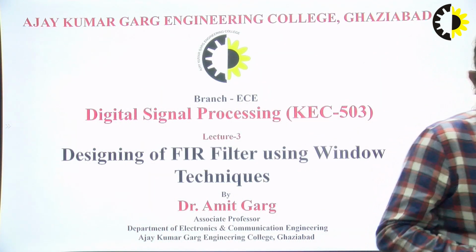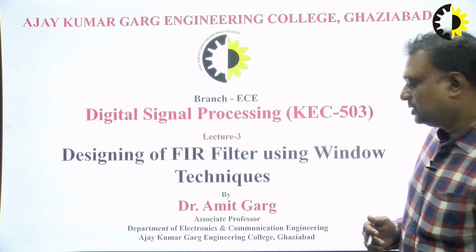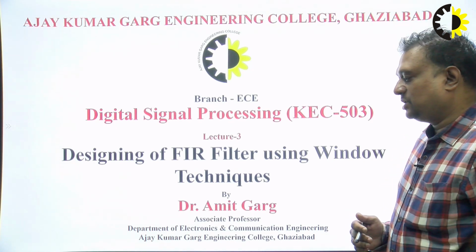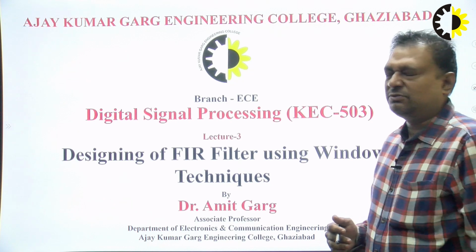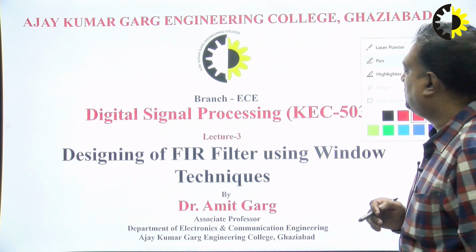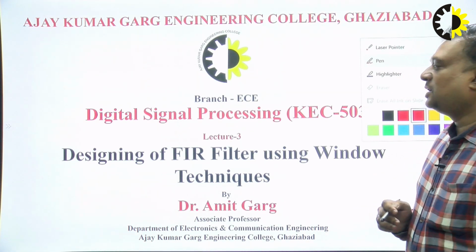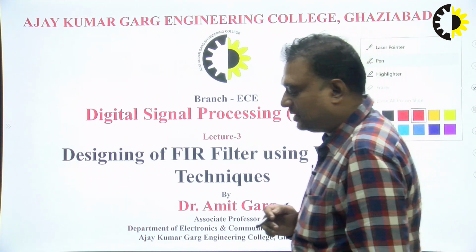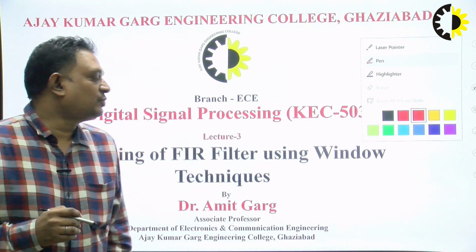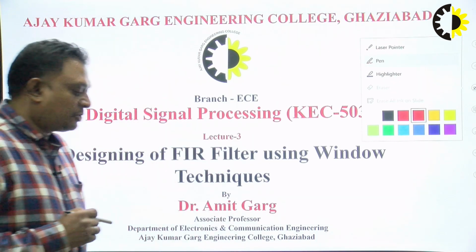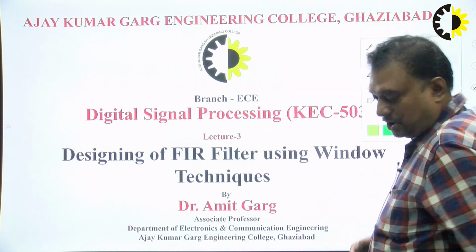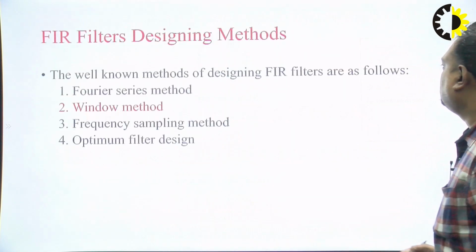In our previous lectures, we have seen the designing of IIR filter. If we talk about the FIR filter, FIR filters are better in terms of designing in comparison to IIR filters because of two reasons. The main reason is that these types of filters are inherently stable systems, and also they have a property called linear phase property, due to which these filters are useful. Whenever we require linear phase, then we have to go through FIR filters as compared to IIR filters. Okay, so let us start with the lecture.